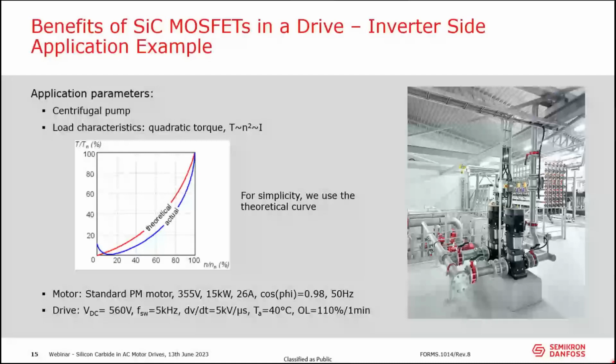you have to run a thermal simulation, and with that thermal simulation, we can go into our lifetime model and calculate the power cycle that comes out with that condition, and we can tune it in one or the other direction. So you can't get there without doing this thermal and lifetime calculation, and then select the right module for the right application. Right. There's no general answer. You have to look into the details.